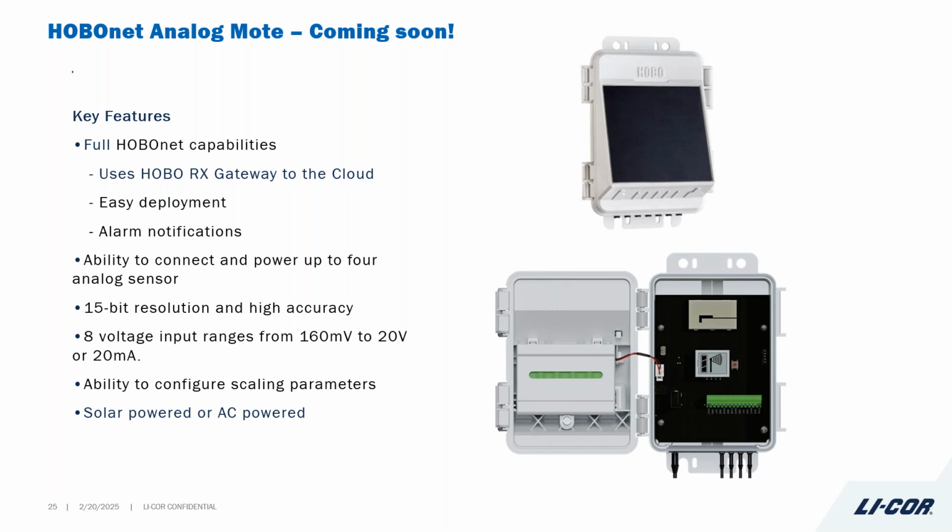It's got a wide range of input ranges, including a 160 millivolt range, which is good for some of those low output sensors, such as light sensors, for example. You get better accuracy when you connect them into that narrower range. It also has the ability to scale to user units, of course, linear scaling. And it's either solar powered, as you can see, it's got the built-in solar panel, or it can be AC powered.